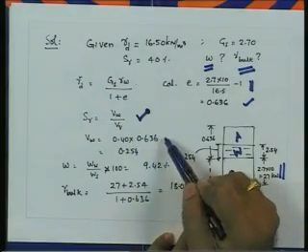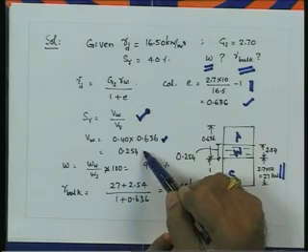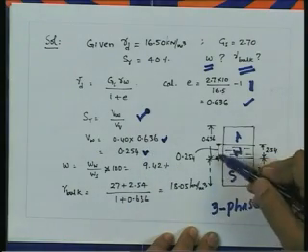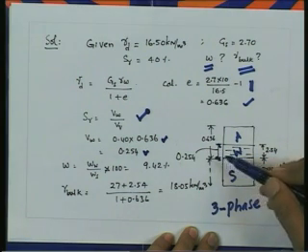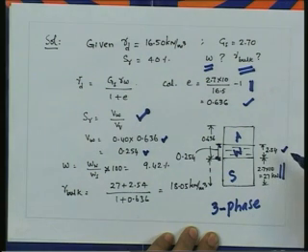So, from the degree of saturation definition, the fundamental definition is nothing but degree of saturation is equal to volume of water to total volume of voids. We knew that degree of saturation is 0.4, that is 40%. So, volume of water is equal to 0.4 times 0.636, which gives volume of water as 0.254. So, we have obtained the volume of water, it is a component of the volume of voids. By knowing the volume of water, we can determine the weight of water, that is 0.254 into 10 is 2.54, that is the weight of water.